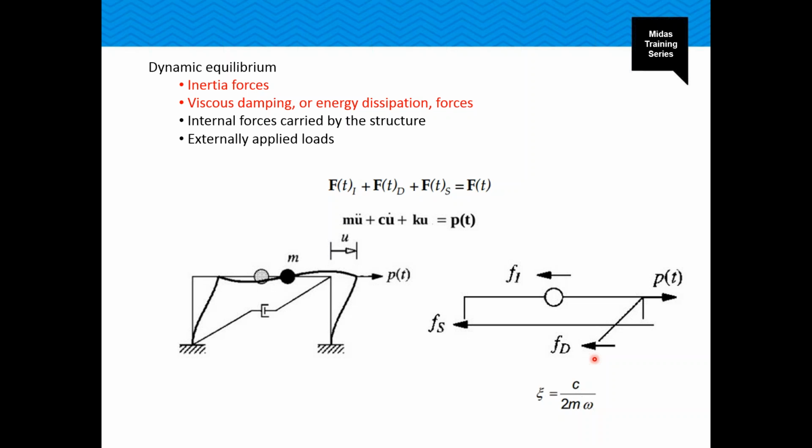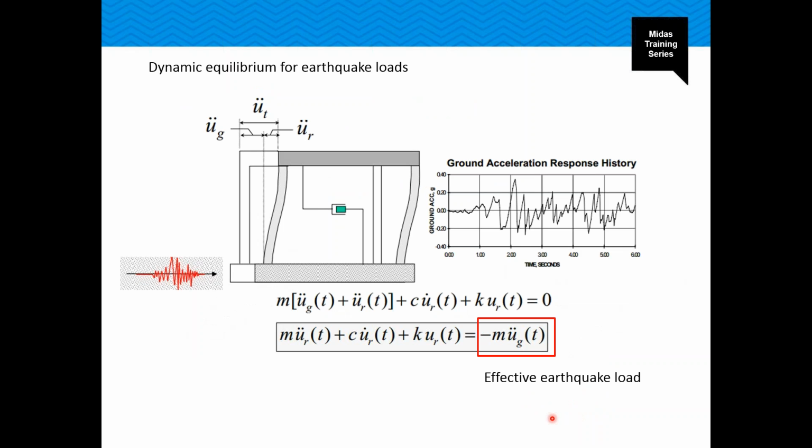The damping of a structure without any added dampers is called inherent damping. It is impossible to describe this inherent damping mathematically. So, the damping coefficient is generally determined from the damping ratio using this formula. The damping ratios are typically assumed to be 3% for steel structures and 5% for concrete structures.